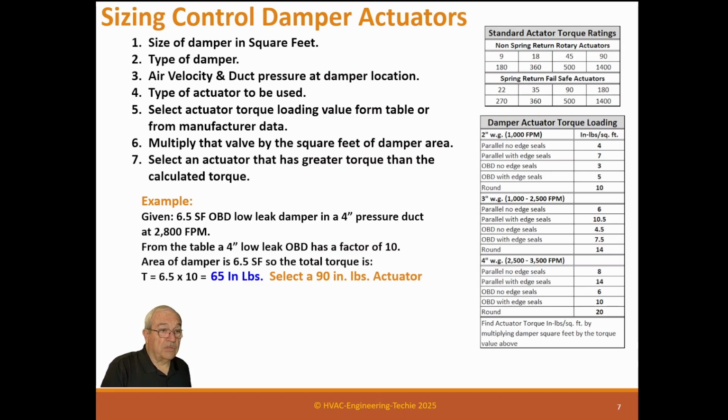It was about 140,000, 200,000 CFM. I don't remember, but it was a whole bunch of mixed axial fans with lots of horsepower, and they started them up. I was sitting in the space and watching the damper start fluttering. It started vibrating violently, and then it had enough force to overcome the actuators and slam shut and move the wall about a foot. So they had to tear that whole wall down and rebuild it. So it can be catastrophic, but it's only in unique circumstances. So try to do your damper actuators correctly.